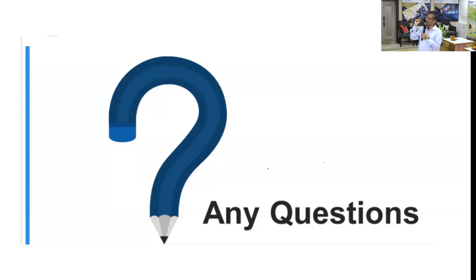So you have to put your knowledge to use. This is the condition: should I go for a drained condition or an undrained condition? Is it a temporary structure or a permanent structure? Can they provide proper drainage or not? Considering all these things, we find out the parameters by conducting appropriate tests.